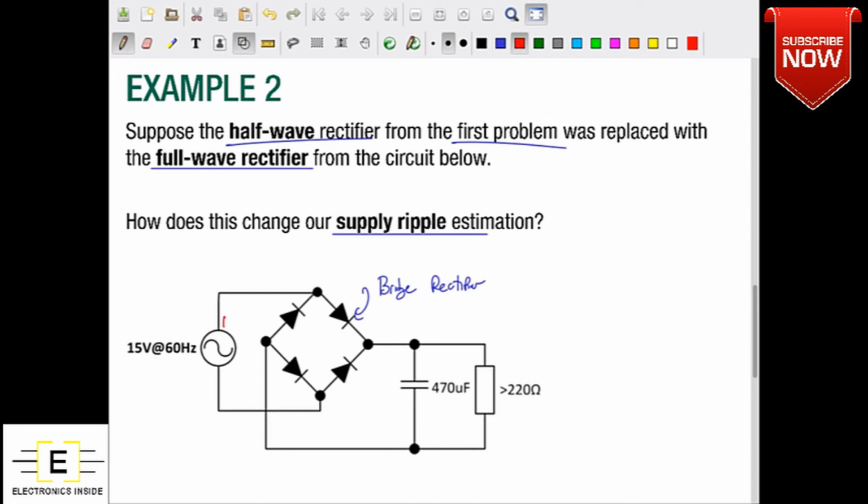Now we know that when current flows, let's say in this direction, it has to pass not just through the load, but through 2 diodes. So not just one diode and the load, but now 2 diodes. And what that's going to do is reduce our maximum rectifier output, the maximum voltage delivered to that load, from the 14.35 volts we had, which was Vin minus our forward voltage, to now we have 2 diode drops. So our Vmax is that maximum input voltage, which we said was 15 volts, minus 650 millivolts times 2.